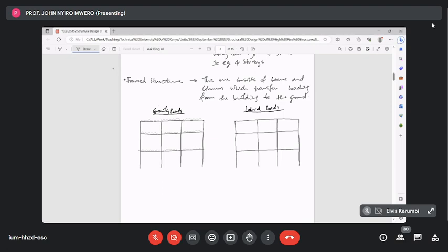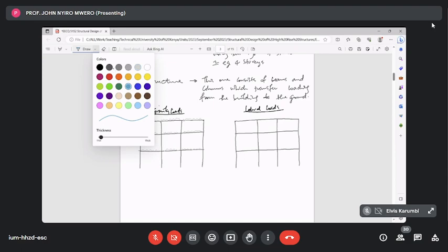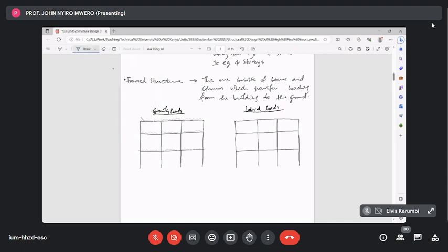Courtesy of those gravity loads, on the beams we would have this kind of bending moment diagram. From your analysis of structures, you know that for a UDL you'd have a parabolic bending moment diagram like that.